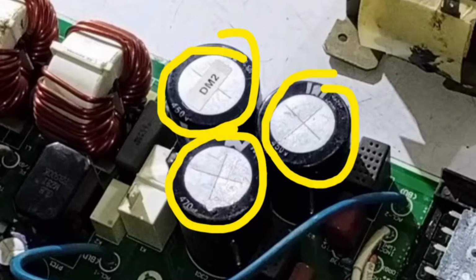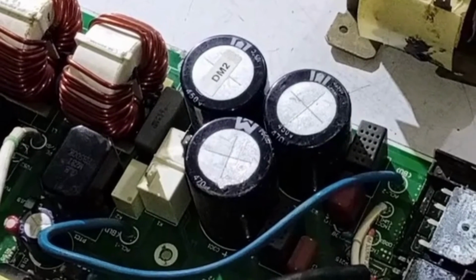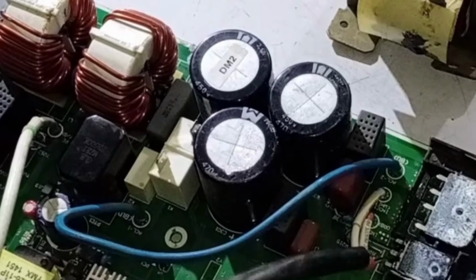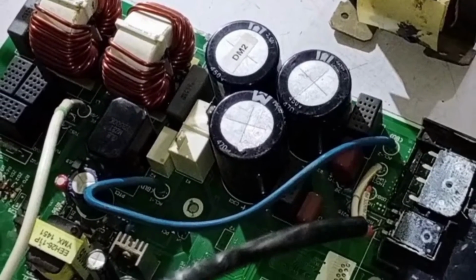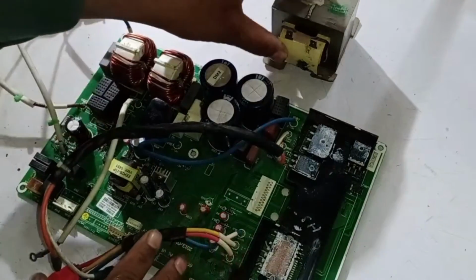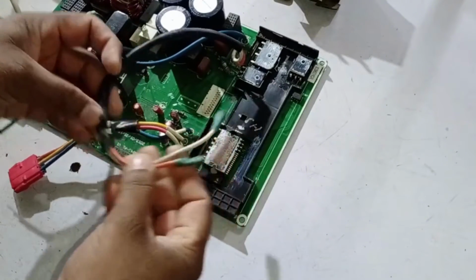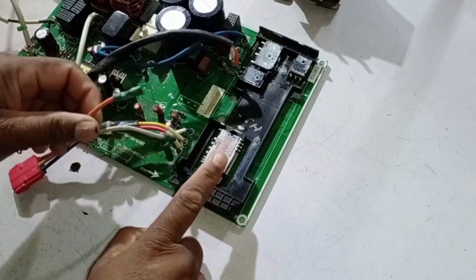Additionally, if any of these 3 capacitors are faulty, you might still see correct voltages. However, if there's a short circuit or any issue with these capacitors, it can still cause problems. You should remove these capacitors from the system and thoroughly check them. If their capacitance value has weakened, replace them to eliminate spikes and fluctuations in the system to make the system work normally. Now, if despite all this, the issue still isn't resolved, you'll need to check the voltages between the wires of these reactors and the IPM, Intelligent Power Module. I'll explain how to do that.